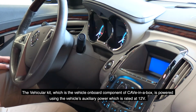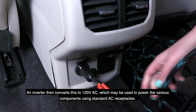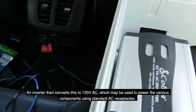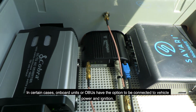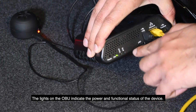The vehicular kit, which is the vehicle onboard component of Cave-in-a-Box, is powered using the vehicle's auxiliary power, which is rated at 12 volts. An inverter then converts this to 120-volt AC, which may be used to power the various components using standard AC receptacles. In certain cases, onboard units or OBUs have the option to be connected to vehicle power and ignition. The lights on the OBU indicate the power and functional status of the device.